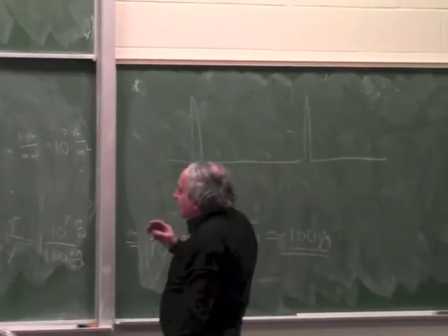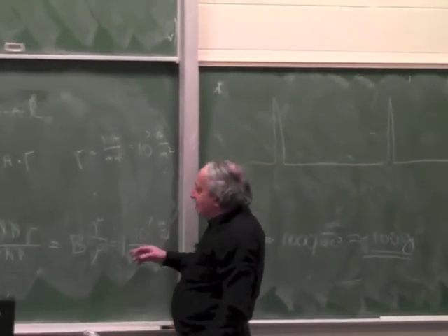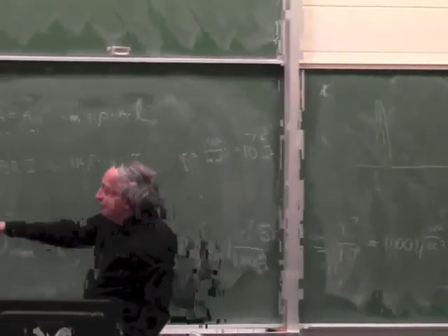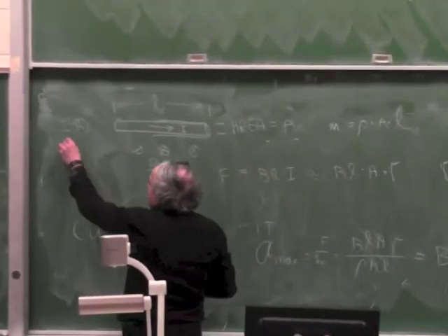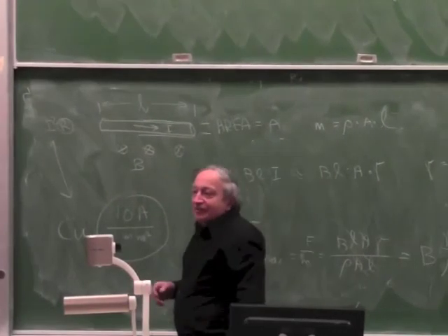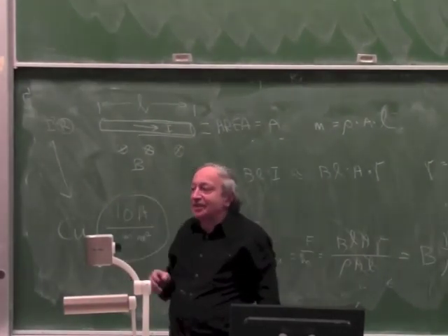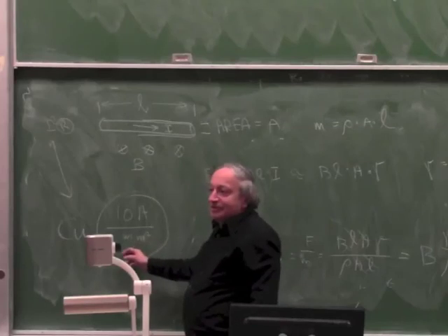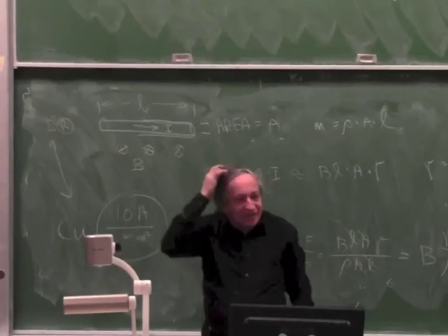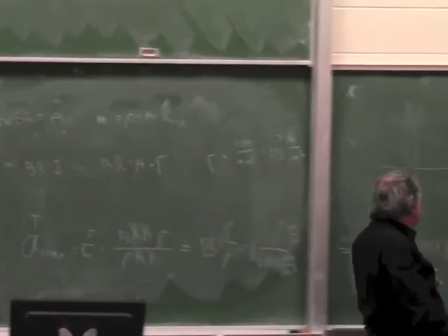But momentarily I can exceed this current by far, because this limit is because of heating, and if I only need to drive it infrequently with a pulse, I can greatly exceed this number. So this is a steady state limit.